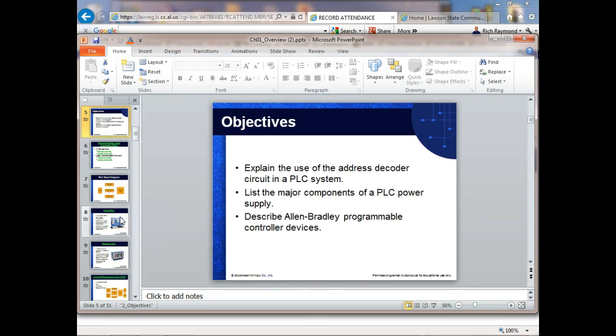They'll say we used to, when we made these EEPROMs, or these programmable devices, we called it burning. We said we need to burn a new ROM. And this came from the technique of PROMs, where we actually literally went in there and blew fuses inside the chip to generate that. So we called it burning. Well, when they came out with these double EEPROMs, the term is usually changed to flashing. So if you hear the term flash memory, that's where flash memory comes from. And these are devices that we can electrically erase and reprogram.